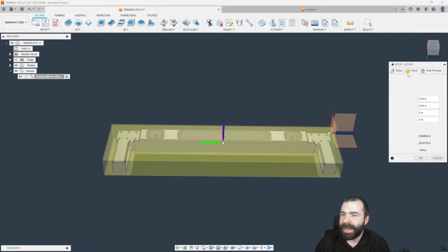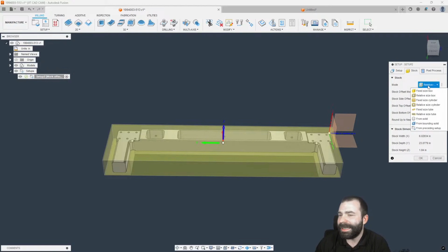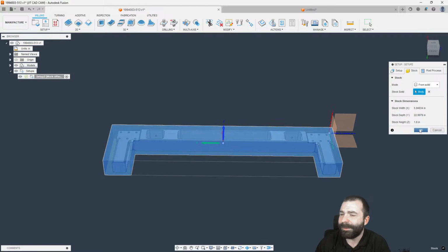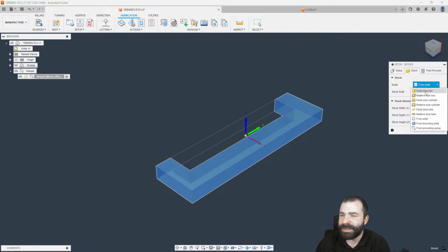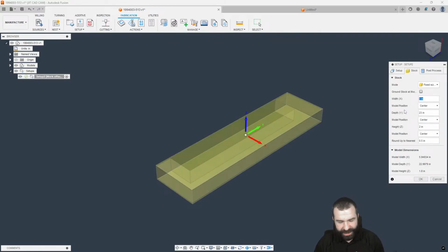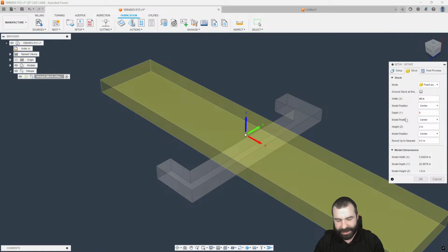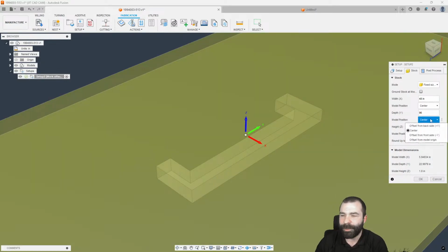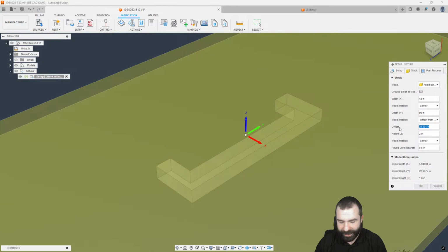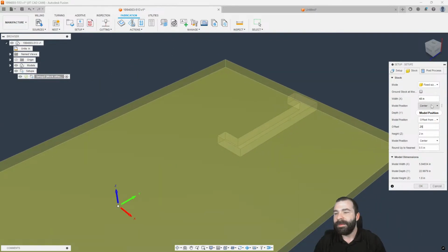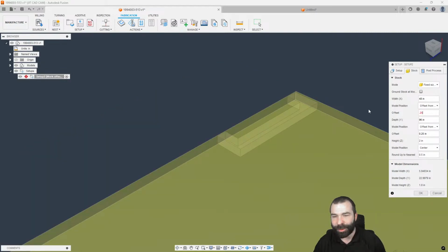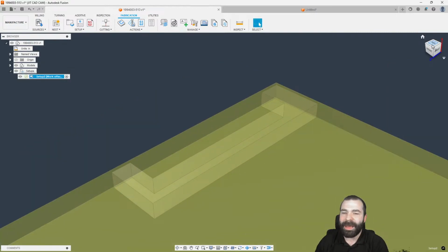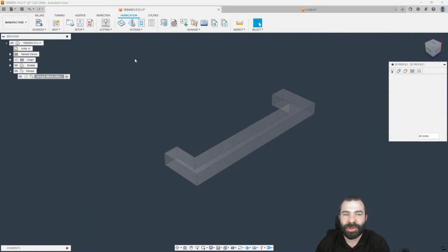And then in our stock, now our stock is technically the exact same model that we're going to machine. Or in this case, we're going to water jet. So I'm going to highlight both. Or if you wanted to set this up as if it was a sheet of material, we could, of course, say it's like 48 by 96. Or we could nest this out, of course, and offset back left, a quarter of an inch or something. Again, the idea here is I'm giving you guys the absolute bare minimums, a rough workflow. But now that we have that, we can go in and hit our 2D profile.